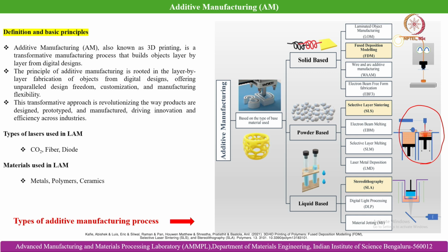basically build the part. Whereas in case of DED, direct metal DED or DMD, whatever you may call it, in the DED process, basically the laser head and the nozzle from where the powder gets deposited on the workpiece, in situ the powder gets deposited and the laser cures it. So, the powder gets deposited with the coaxial nozzle and the laser cures it. It is a simultaneous process,